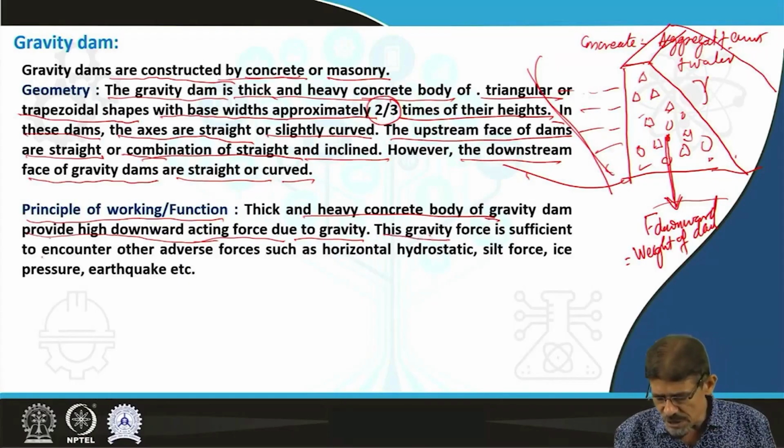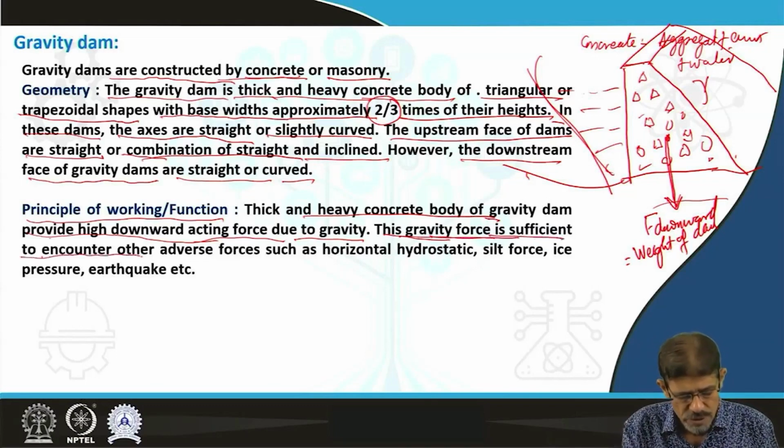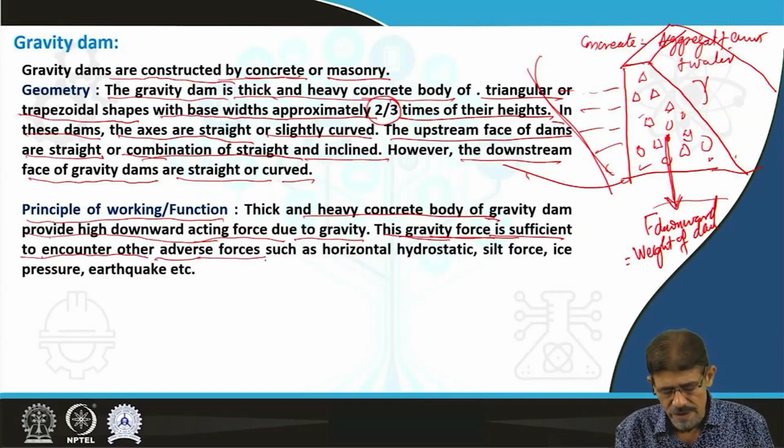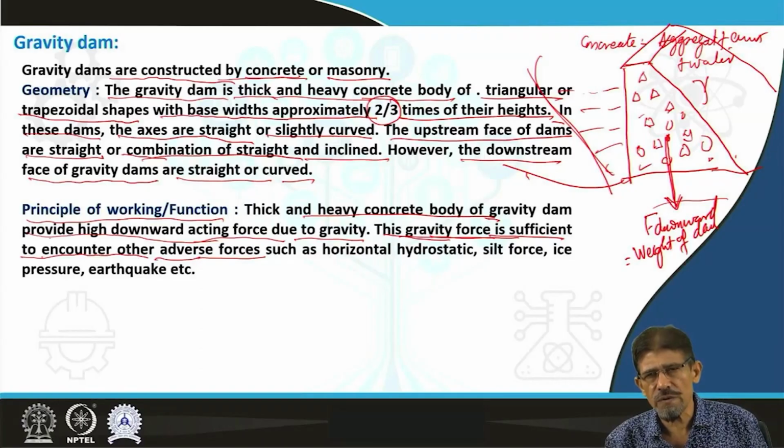This gravitational force or gravity force should be sufficient to counter other adverse forces like horizontal hydrostatic force, silt pressure or silt force, earthquake pressure or force caused by seismic activity, force caused by the dynamic state of water, force caused by ice, change in state of water, etc.